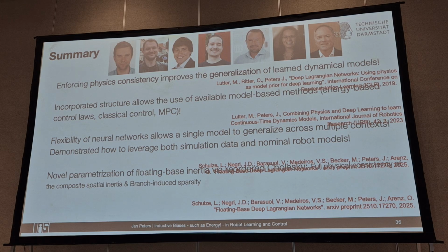Yes, there's actually a fundamental difference. And you don't even need to look at this work. You can go quite a bit back to my student Duy Nguyen-Tuong, who already showed 15 years ago the big advantage of learning-based methods at that time, based on kernels, which also have the squared form of the inertia term here, by the way, is that you would locally always have better performance and you would not actually need persistent excitation that crazily because your parameters did not have such a big global effect.